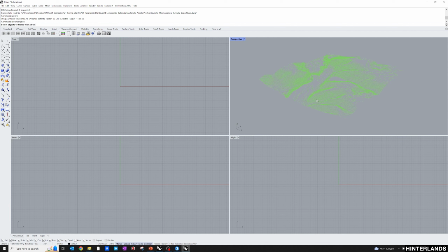But if we check the distance of either this side or the other side, we see that it's 790 feet. Now this is actually too small because, as we know, we created sides that were 2,500 something feet. So we're going to need to resize those. And essentially what it's done here is it's brought in the meters and it's reading them as single units, as feet.